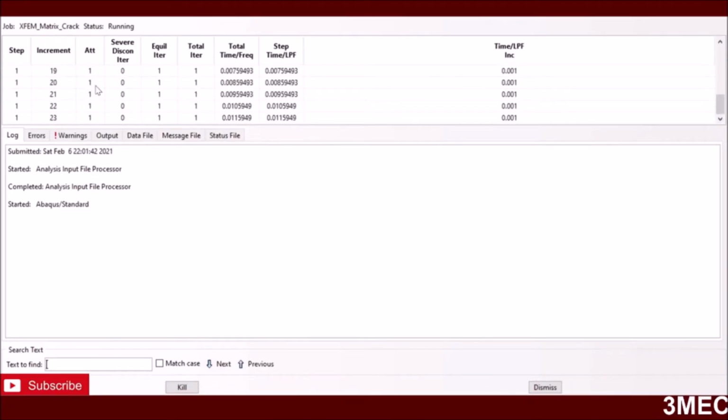This means that point might be the place where your elements start to delete, or your stiffness starts to get negative in those elements which are failing. You see here a lot of them, and that will cause the time increment to go down in many cases. Then again, when it becomes stable, where your next element is loading, then it's fine. But as soon as it starts to fail, you will again see some issues with the convergence, and then again it caters for it as well. So solver is okay because we have used stabilization option, and I'm using line search as well. So it seems to be okay to me right now, and hopefully it will go through everything well.